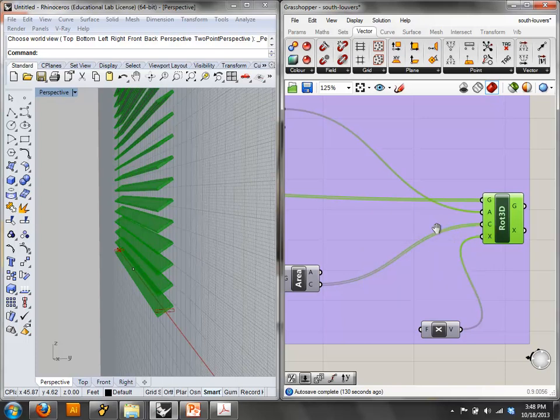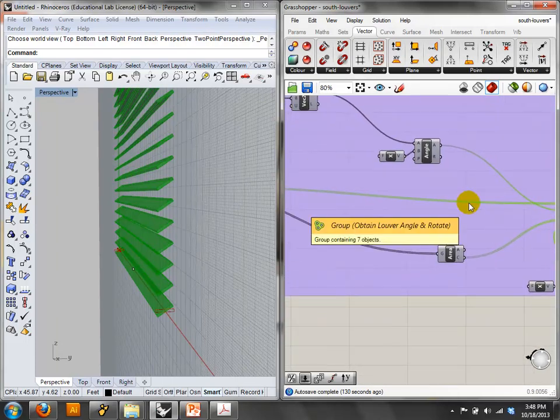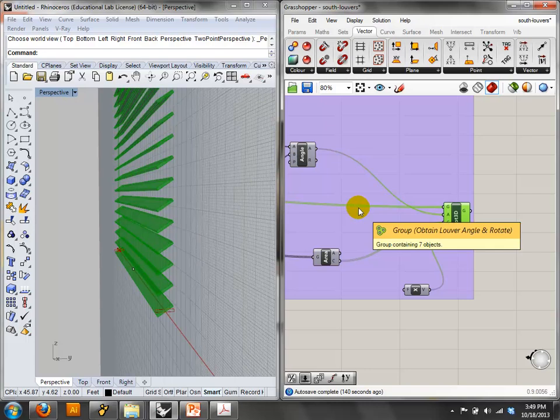I'm sorry, I didn't mean to go through that. So yeah, and it doesn't have to be a rectangle. It could be some form that you create, as long as you can find a way to find that axis somewhere. Even if you just make it arbitrary, that's how it's going to work. Okay, does that explanation make sense for finding the axis? It's easy if it's a surface, right? Because then you can just take the edge too. You can take the edge of it, use it as a rectangle, and then extrude it to create a solid. It doesn't really matter. It's just a matter of different ways to end up with the same result. But you do want to be able to control it.